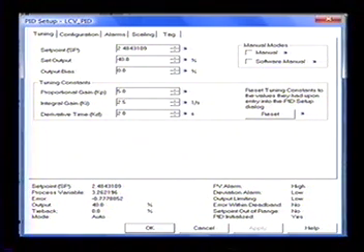And then down here at the bottom, you can actually see your set point, your process variable, and your error, right? You can see that your output is open 40%, your tieback is 0%, and your mode is in auto mode, so it's actually in auto mode. You have a process variable alarm, high, deviation alarm, low, output limiting, low, error within deadband, no.